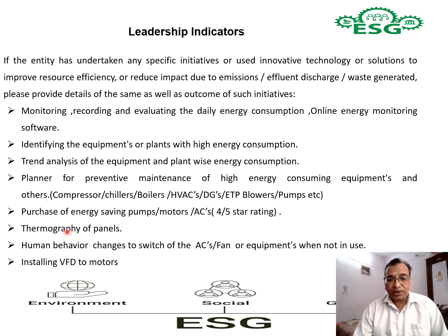Then while purchasing, you have a purchase policy also. You have to take the purchase department into confidence, so that when they purchase, they see that they purchase the pumps, motors or equipments or ACs which have 4 or 5 star rating. Preferably you go for 5-star rating, so there are very less energy consuming equipments. Then you can go for thermography of the panels. You can have an individual planner for this, and this is to prevent the overheating and minimize the losses.